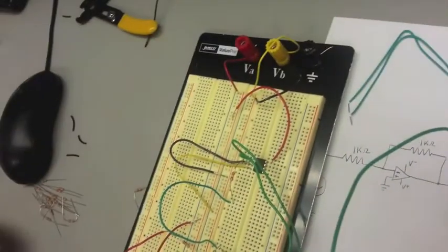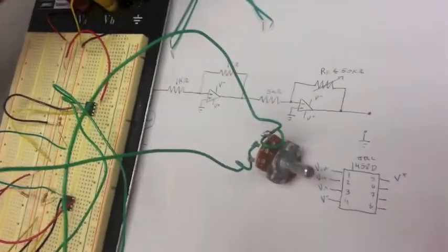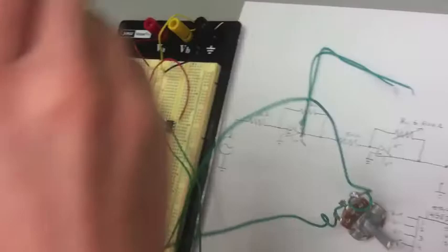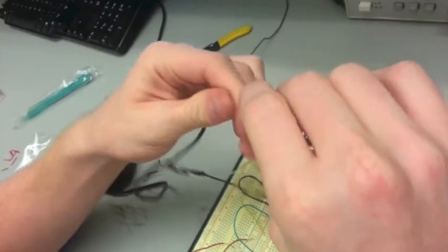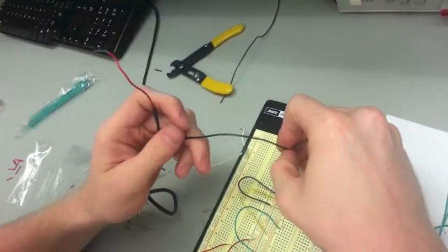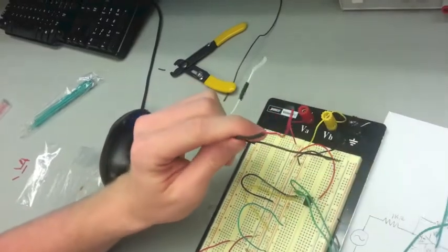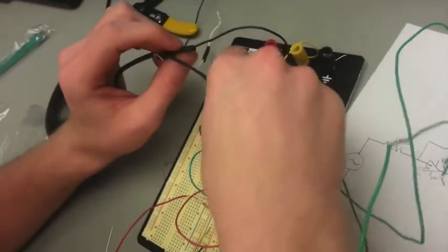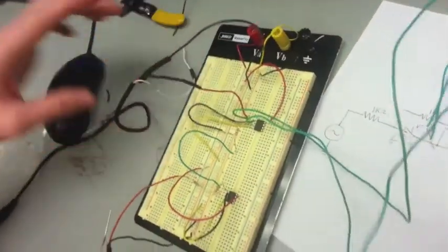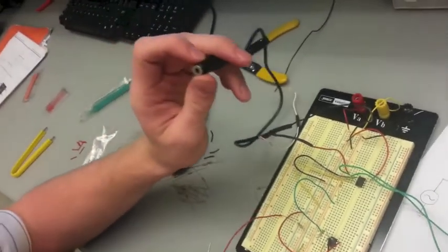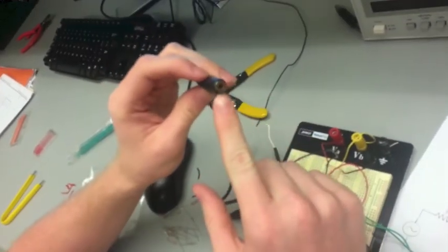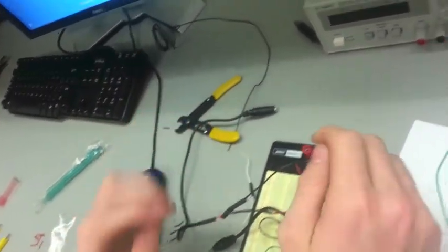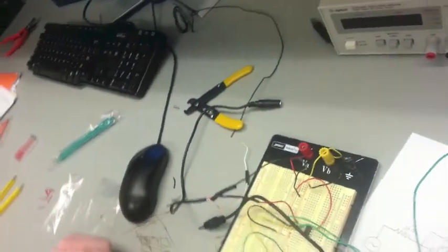And now we're going to get to our output. So we're going to take the red wire and black wire, and just as before, the black wire goes to ground. And the red wire will go to pin 1 with where the output is. And there you have it. All you have to do is plug this side into any audio source and have any kind of speaker or headphones in this side, and plug your breadboard in and you'll have a speaker with an amplifier.